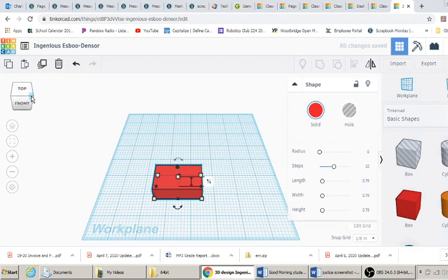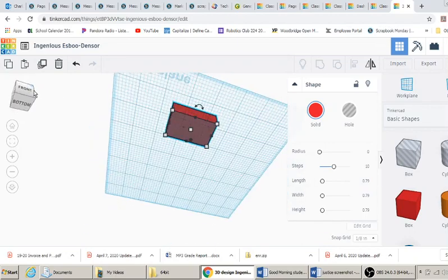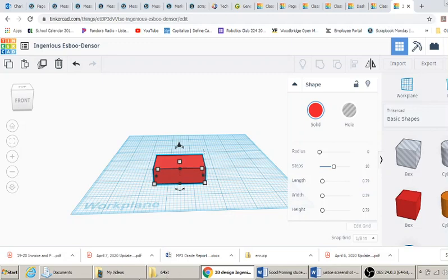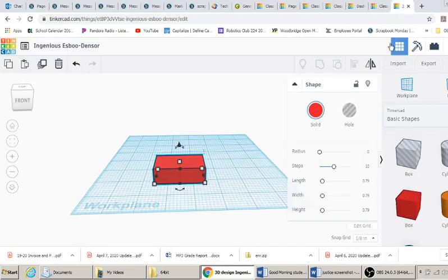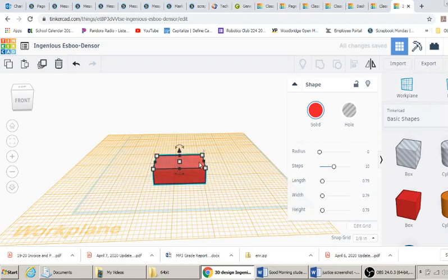This is where students now had a little problem. They needed to create that second block up here, which is 1 inch wide by 5/8 inch high. You cannot do it on this surface here. You need to create a new work plane, so I select the work plane tool, and I click on that surface, and it creates a brown surface.